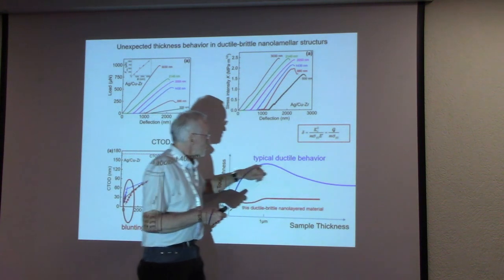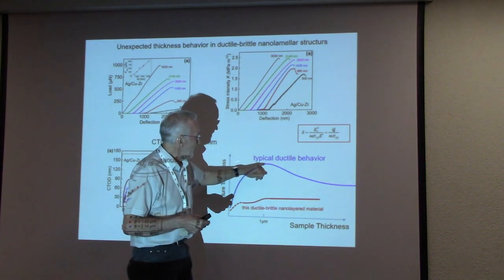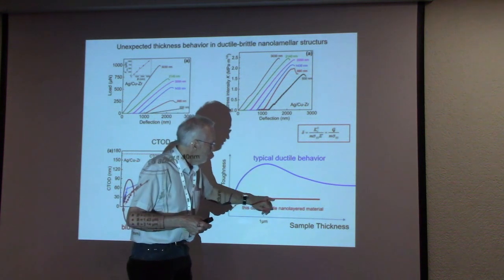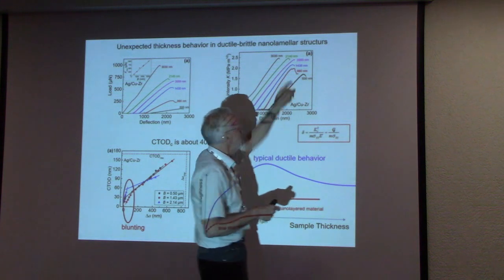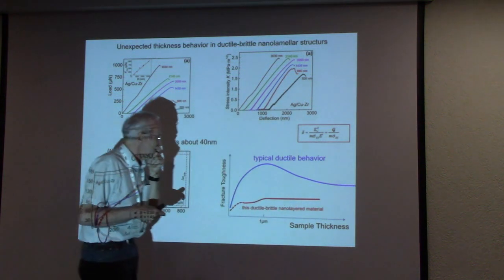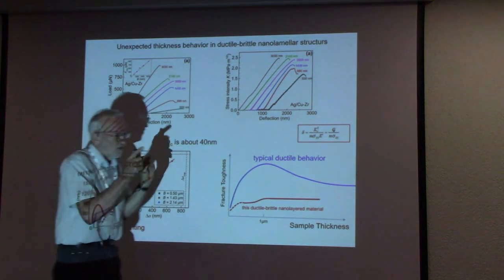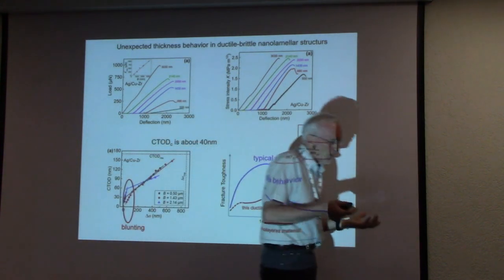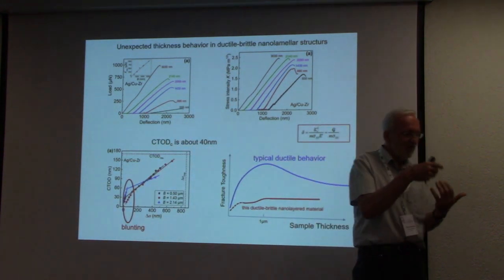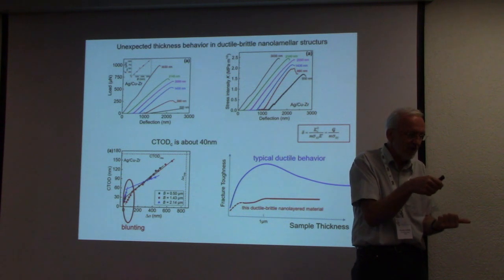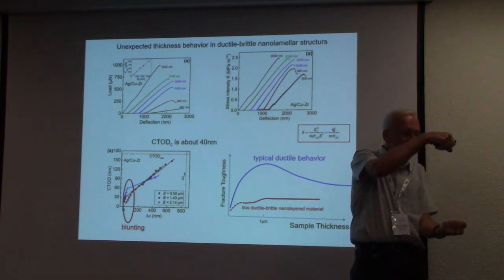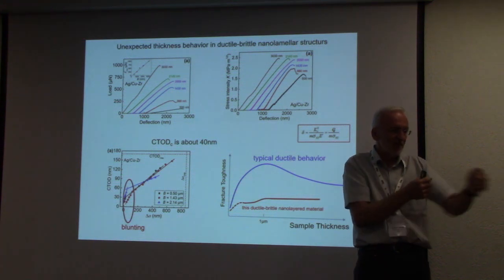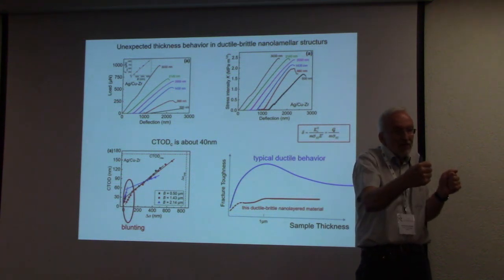And then in our sample, it is now different. In the very thin samples, also the growth of the pores is significantly reduced in the plane stress case, because in the plane strain case, we have enormous high stresses in the loading direction, in the thickness direction, and in the crack propagation direction.